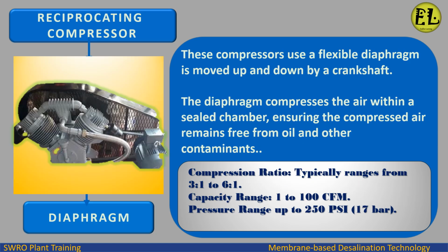Reciprocating compressor divided into diaphragm. These compressors use a flexible diaphragm that is moved up and down by a crankshaft. The diaphragm compresses the air within a sealed chamber, ensuring the compressed air remains free from oil and other contaminants.